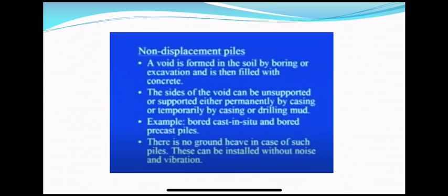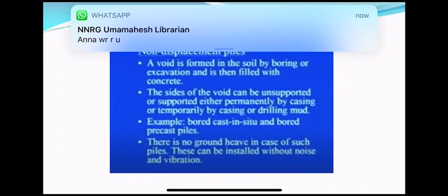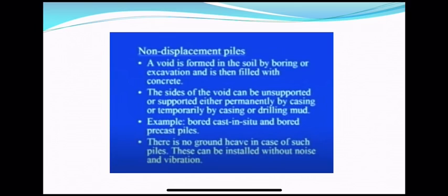And bored cast in situ piles. Here I am introducing this new term, bored. Earlier, the method of installation was with the help of some mechanical measure, that is, by hammering or vibration. But in the case of bored piles, first the void is created, which is usually called a borehole, and then the concrete is cast on the site itself, so that becomes a bored cast in situ pile.